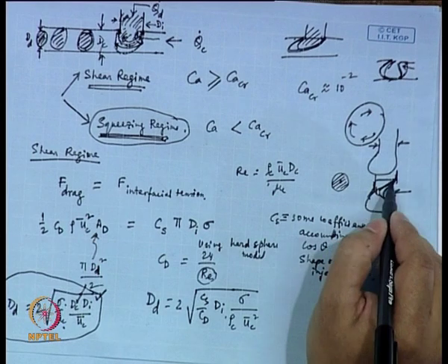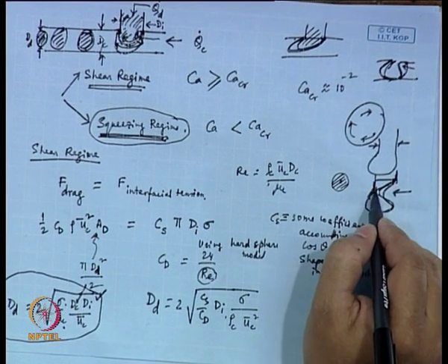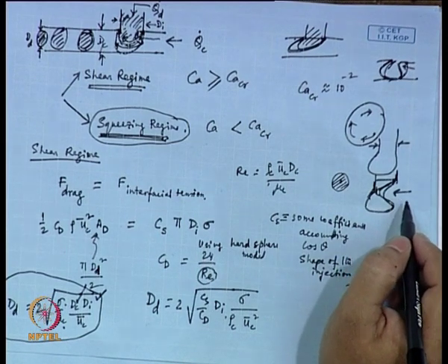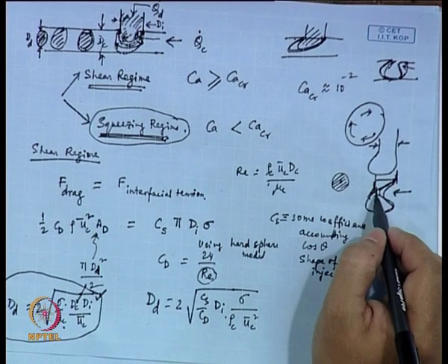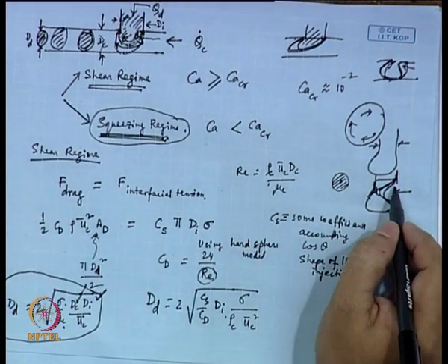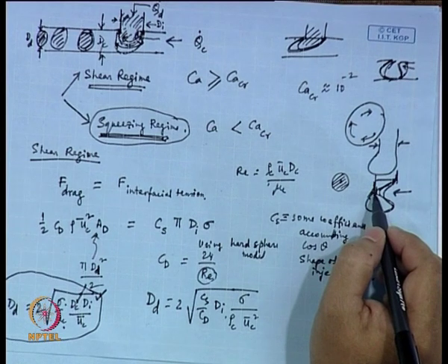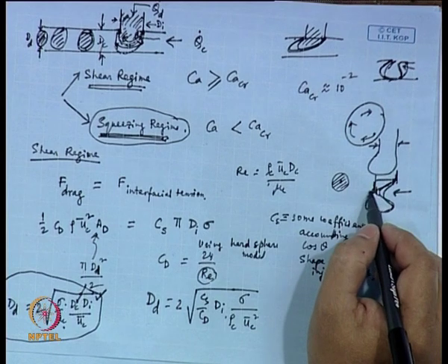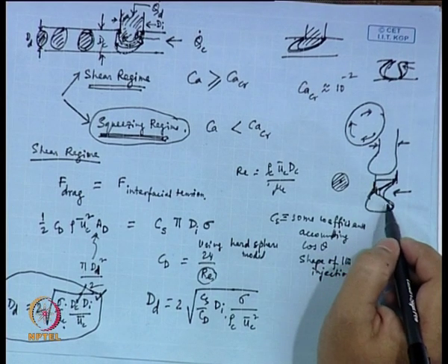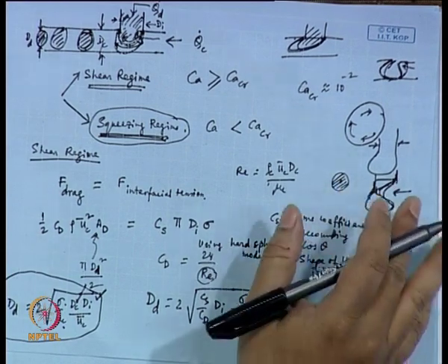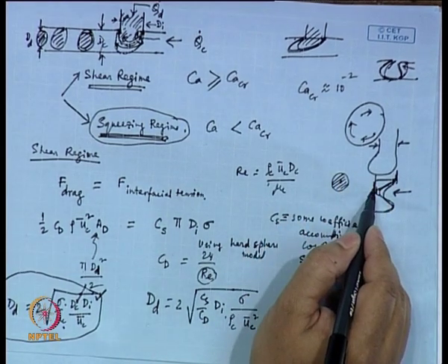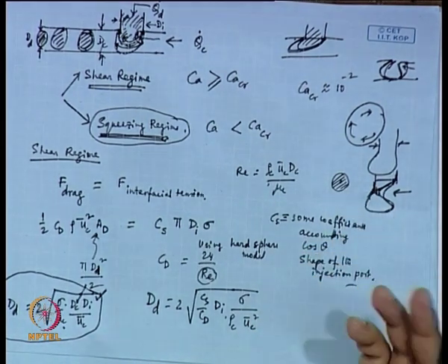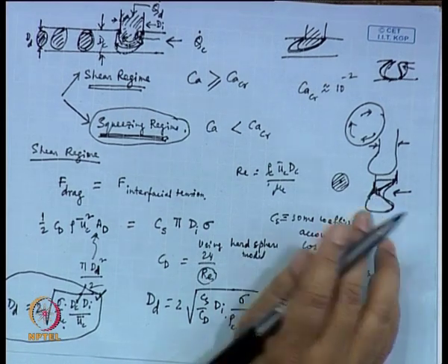I mean, if you do not want to go by the geometry, you can say when this thickness gets 0, because this QC dot that you have is fixed, that is constant. So, it has to eat away, and the rest of it is geometry. Now, you can say that okay, it will reach the end. When it reaches the end, I will consider the droplet to be released, or you can say that okay, still there is some delta left, and at that point some Rayleigh plateau instability caused this to rupture, because here it is a neck. So, at some point there is a rupture. But anyway, that delta would be very small.